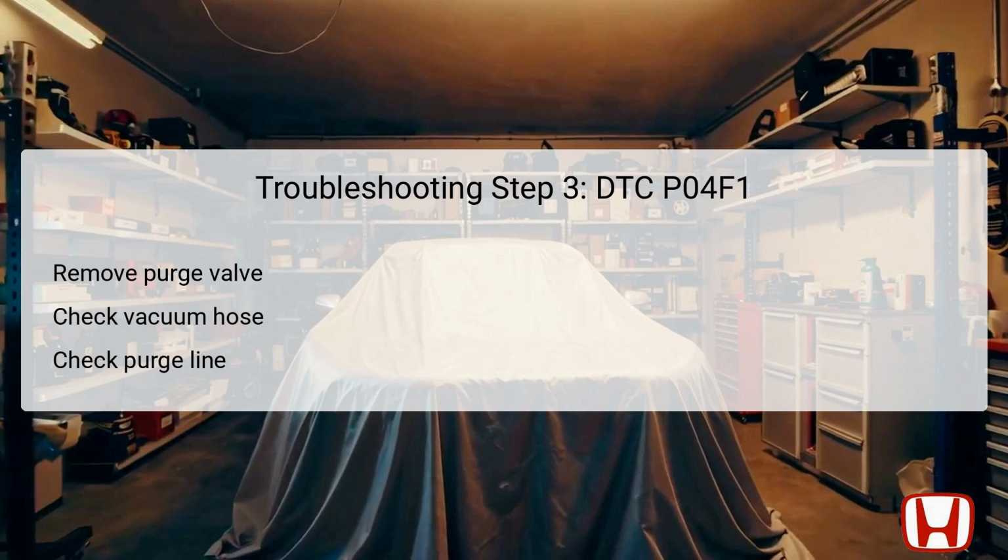This test is essential for determining if there are blockages present in the line that connects the purge valve to the EVAP canister. Documenting the vacuum gauge's reading will guide further troubleshooting.